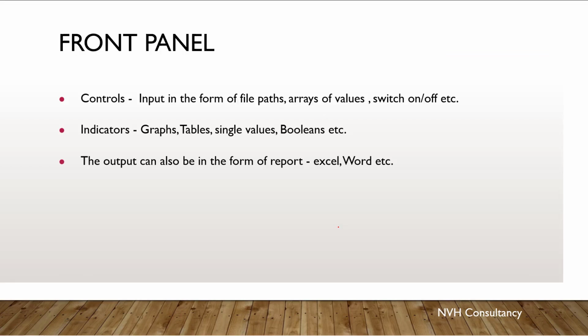So how will the front panel look? The front panel will host the controls, that is input in the form of file paths, arrays of values, and switches for on and off. The indicators are typically graphs, tables, single values, booleans, etc. The output can also be in the form of a report, that is Excel or Word.